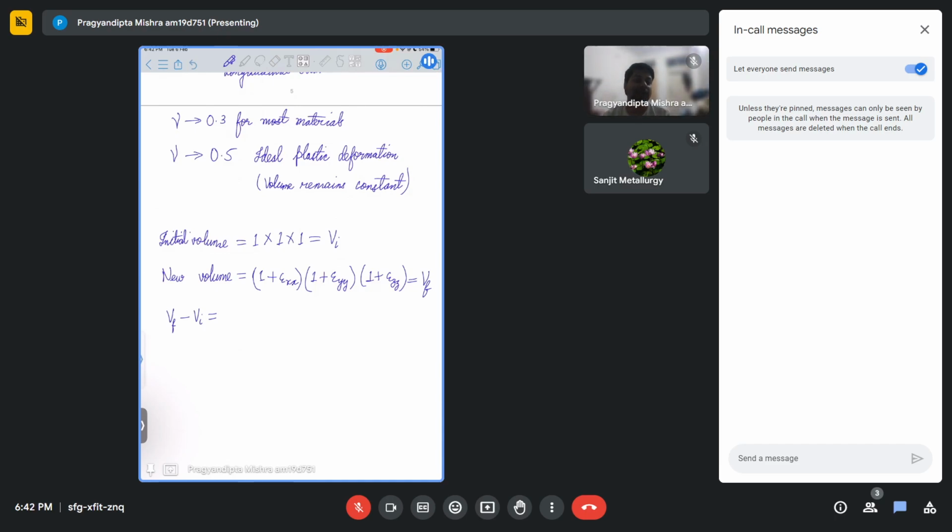If the strain value is very high, it would mean that the material would probably undergo plastic deformation, not just elastic deformation. So if you want to stay within the elastic regime, we usually assume that the strain is small. This is known as the small strain approximation. You're assuming that the strain is very small. So if you multiply one small value with another small value, the resulting value would be even smaller, right?